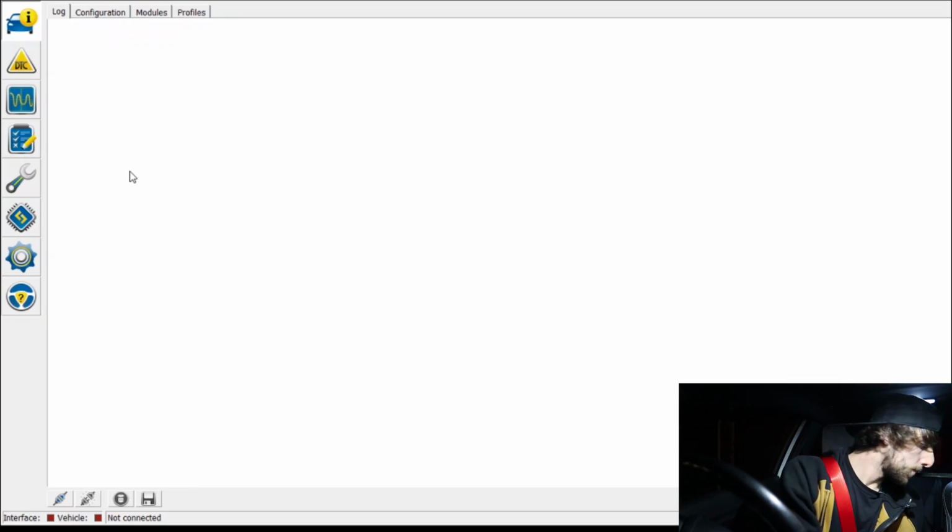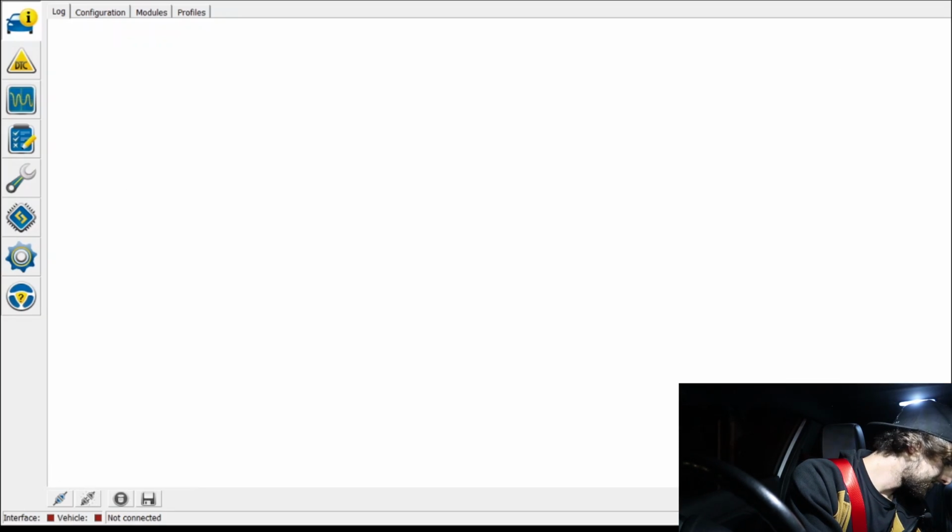I'm making this as simple as I can, but basically it switches between the two different brains and allows you to read the settings that you need. So that's just on a big long USB, and this is what you're going to plug in to your OBD port. Right, once that is plugged in, we're going to go onto the Forscan app, and we are going to press connect down the bottom.